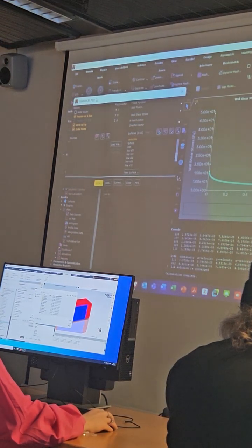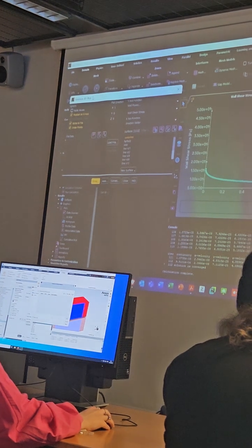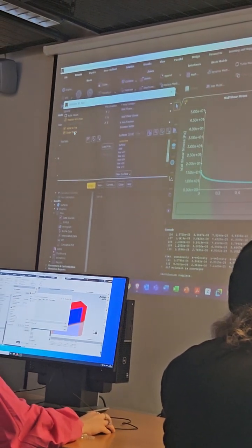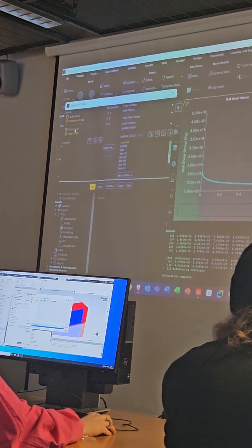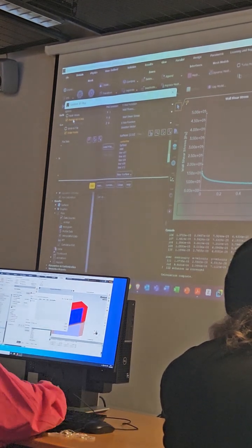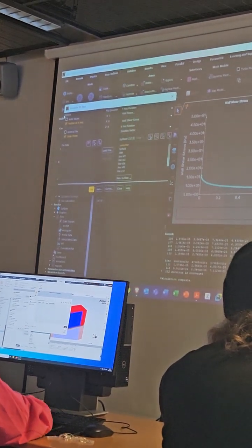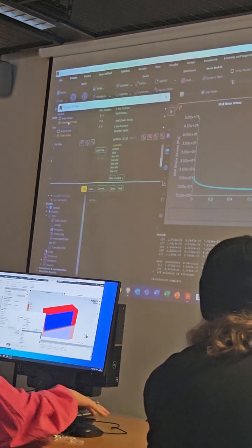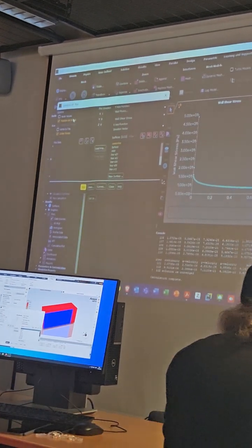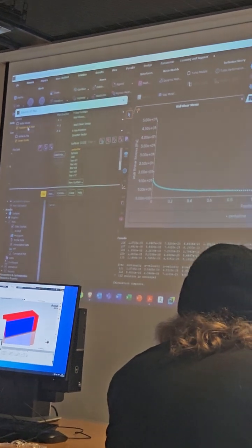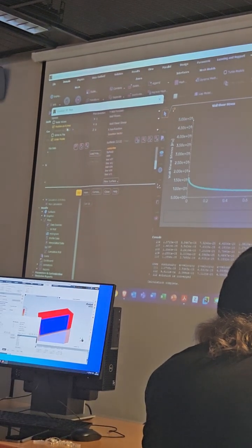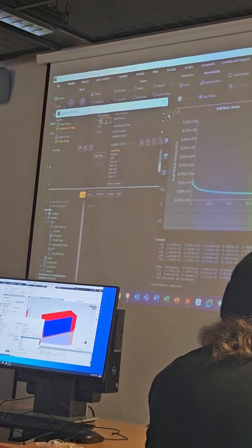Then we can do the same for the lines perpendicular to the plate. Now let's first plot, so I will deselect Write to file. Basically you can choose the x-axis either by deselecting this option and selecting the x-axis on the right, or you can change the plot direction.